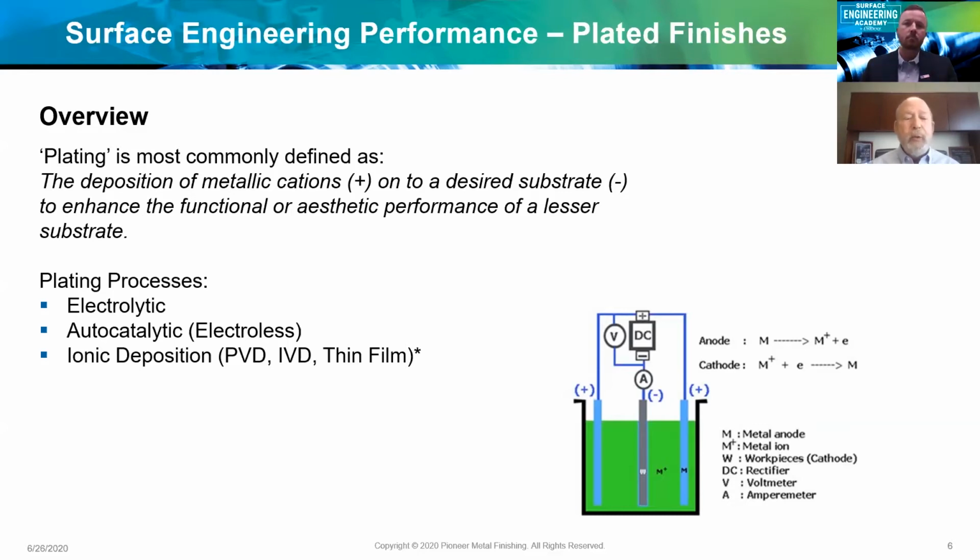And in order to do the electroplating process, you need to have the metal in a liquid state. That's accomplished by dissolving the metal in a strong acid or alkali solution. A natural thing that occurs when you dissolve this metal is it takes a plus charge. And this allows us to take this solution now and put the parts into the plating solution.